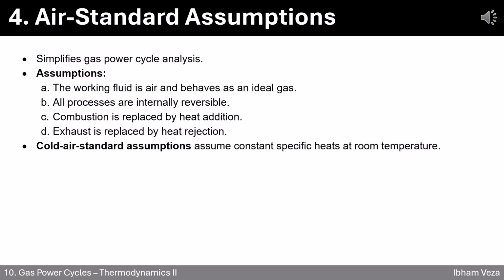4. Air standard assumptions. Let's make gas power cycle analysis easier by introducing some simplifying assumptions. Instead of dealing with the complex reality of combustion and exhaust, we model the system using clean, idealized conditions called air standard assumptions. Here's the idea. First, we assume the working fluid is air and it behaves like a perfect ideal gas. This skips all the chemical reactions and focuses on pure thermodynamics.